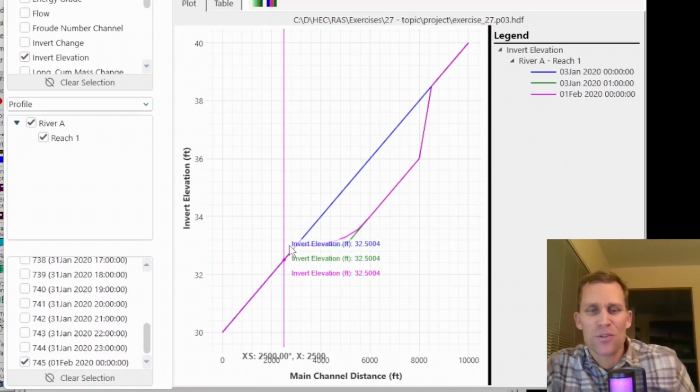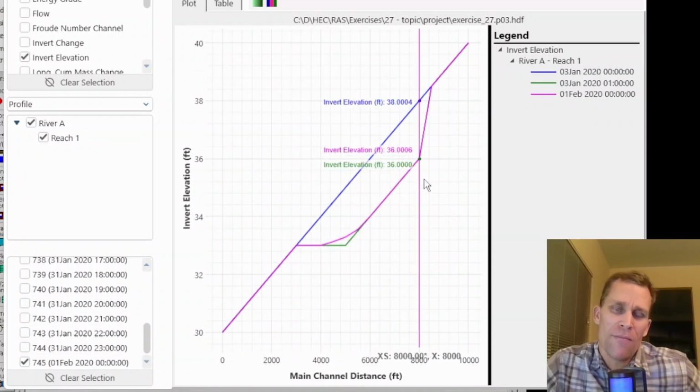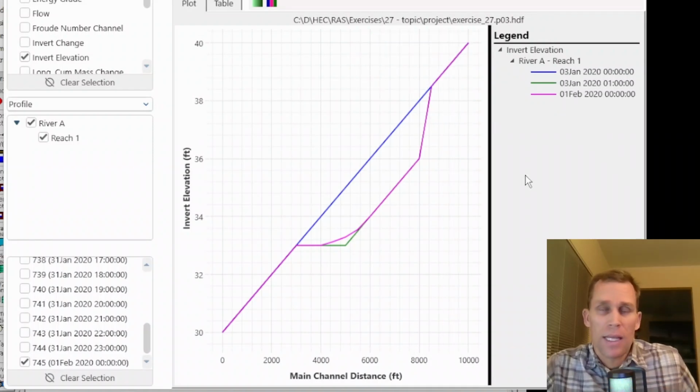Ah, very nice. So the magenta line right here, we see a little bit of deposition, but far less deposition than we saw with 100 CFS flow, because remember, the only thing that we changed was that flow rate. It's a constant flow rate, and because it's higher flows, there's less deposition. It doesn't really matter what method we would use. Higher flows, if you triple the flows, you're definitely going to have more sediment transport and less deposition.